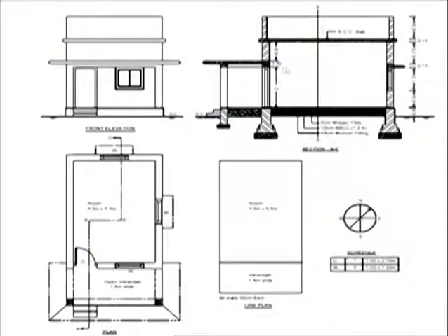Okay, so similarly here also this door is shown, the lintel is there. Sometimes here at this plinth level the DPC is also provided. You may show the damp proof course. The DPC is provided to prevent the damp moisture which is there in the soil, that rises in the walls due to the capillary, and that comes into this wall, and that moisture is affecting the outer surface of the wall.